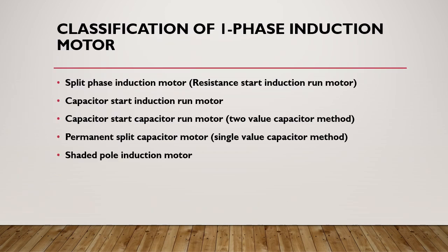First of all, I am discussing the classification of single phase induction motors. There are 5 classifications. The first one is the split phase induction motor, also called the resistance start induction motor. The second one is the capacitor start induction run motor. The third one is the capacitor start, capacitor run motor. The fourth one is the permanent split capacitor motor, and the last one is the shaded pole induction motor.